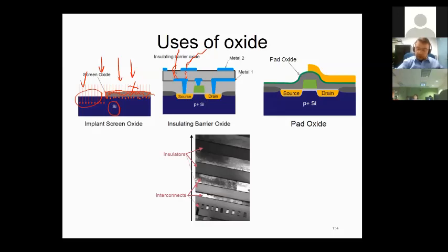Or we can try to smooth out the locations. You can see here, this pad oxide is a thin oxide. Its main purpose is to cover these kinds of areas to smooth out the whole trajectory for the upcoming layer, so that once you deposit the new layer, it will not see this kind of a sharp change in terms of the topography. You see, this is really a huge slope here. It might break and it might create stress on the side walls, and that might put a lot of tension on that little thin layer there.